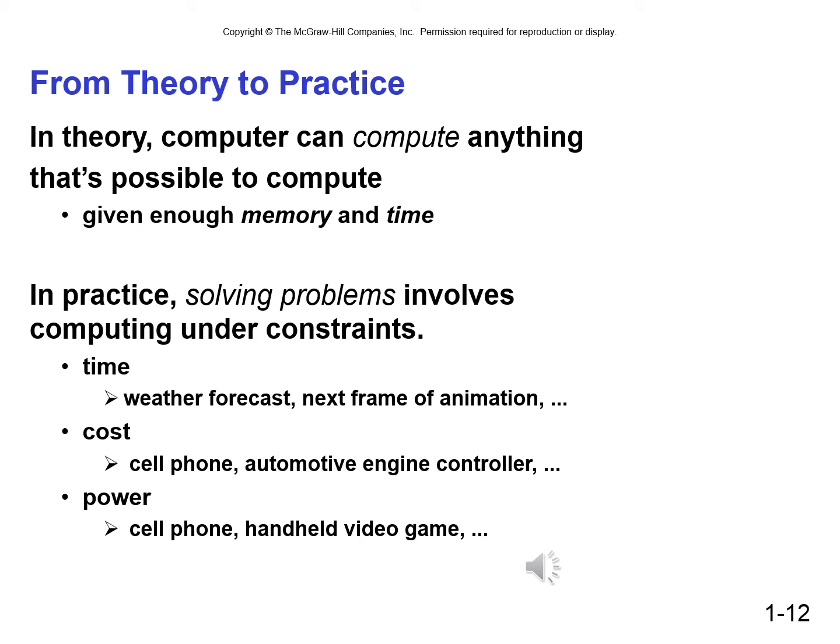mechanical carburation, right? A fuel delivery system that was based on vacuum pressure and various other non-digital inputs, to electronic fuel injection. Obviously, the processor had to be quick enough to meter fuel into a high-speed internal combustion engine at the rate necessary to maintain combustion.